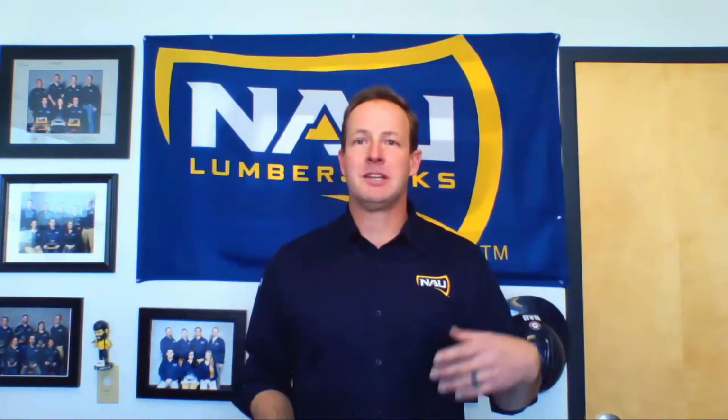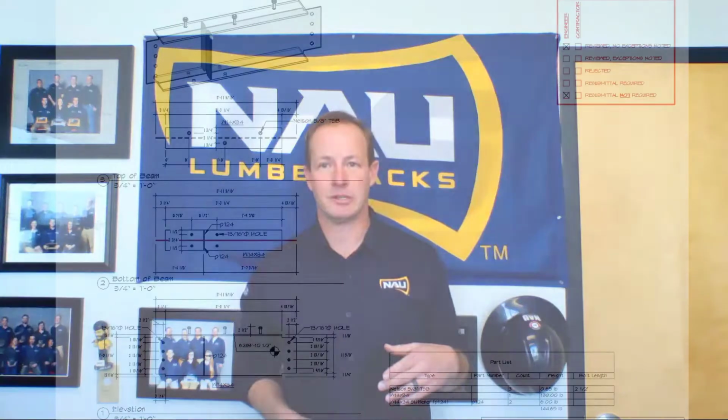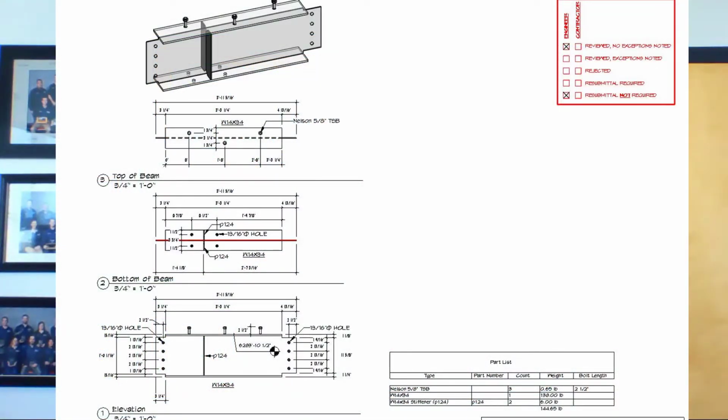Well, a lot of times in the shop drawings, you're going to get more information than you did when you had just the architectural or just the structural drawings. So while the structural engineer may tell you in the drawings that he wants a W10 by 100 column, it'll be needed in this location right here. The structural steel shop drawings will show that column's exact length, what it needs to be cut to.